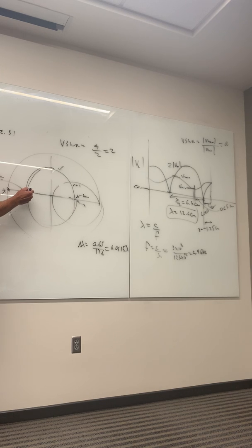When I take a look at this, I see that the distance I have to go to get there is this distance. This has to be a distance of 0.0515 lambda. So here's one way to get it. You can say that's 0 right there, or you can say it's equal to 0.5. If it's 0.5, if you subtract 0.0515 from it, what do you get for this mile marker? Do you see what I'm doing here?